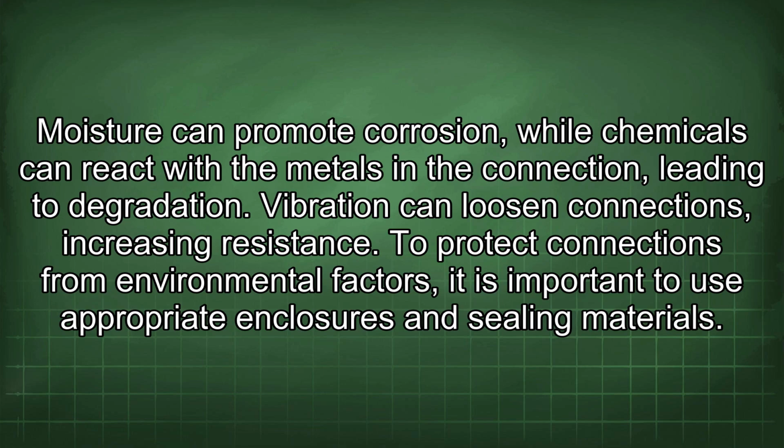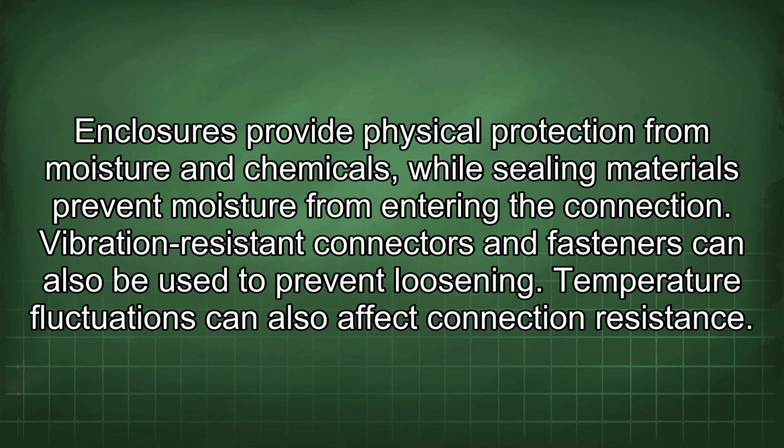To protect connections from environmental factors, it is important to use appropriate enclosures and sealing materials. Enclosures provide physical protection from moisture and chemicals, while sealing materials prevent moisture from entering the connection. Vibration-resistant connectors and fasteners can also be used to prevent loosening.